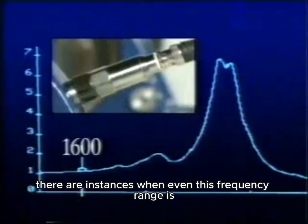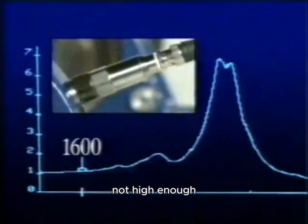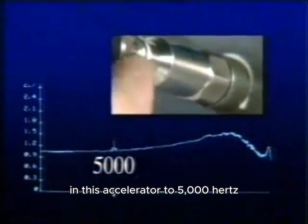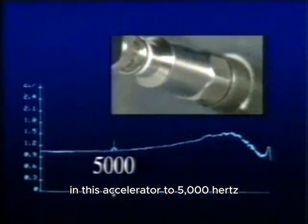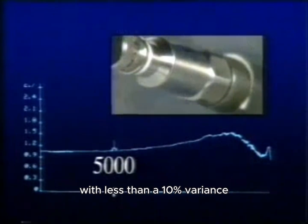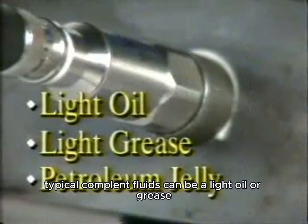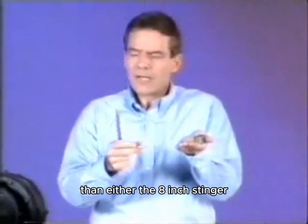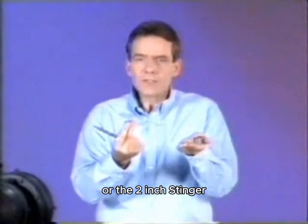There are instances when even this frequency range is not high enough. When a coupling fluid is used between the sensor and the magnet and machine, the linear response range is increased in this accelerometer to 5000 hertz with less than a 10% variance. Typical couplant fluids can be a light oil or grease or even petroleum jelly. All of these magnets provide a greater frequency response range than either the 8-inch Stinger or the 2-inch Stinger.